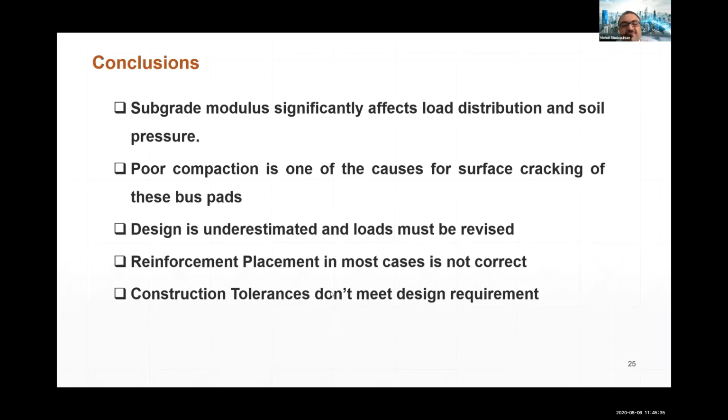Concrete slab failure due to negative moment can be easily monitored and traced, as a crack appears on the slab top face. But failure due to positive moment cannot be identified and monitored as easily, because positive moment cracks initiate from the bottom face of the slab and are not observable. Therefore, more attention needs to be paid to designing the boss pad slab for positive moments.